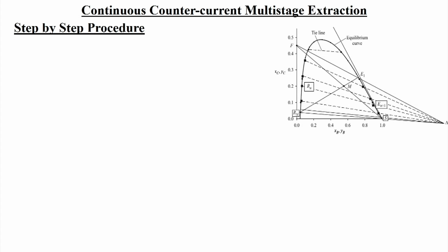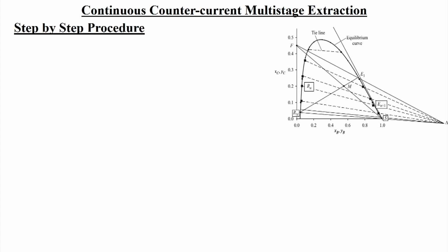Now, we need to draw what I told earlier. If we know the extracting solvent, carrier solvent and solute miscibility, then we have this ternary diagram. We will draw it from the equilibrium data points, and we get the binary phase zone by drawing the equilibrium line. Suppose this is the plait point. The left hand side will be the raffinate arm and the right hand side will be the extract arm. This is common to every extraction stage.